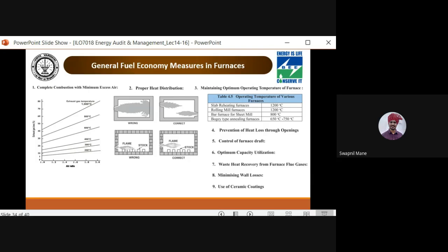Okay, if the furnace pressure is slightly higher than outside air pressure, then what happens? Basically, the furnace inside pressure is kept higher than the surrounding to minimize the infiltration rate. If the furnace inside pressure is lower, then infiltration will take place.